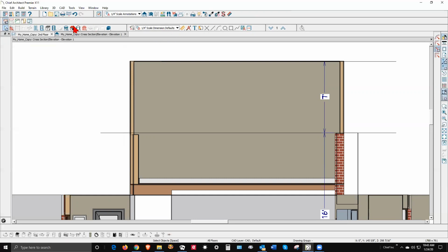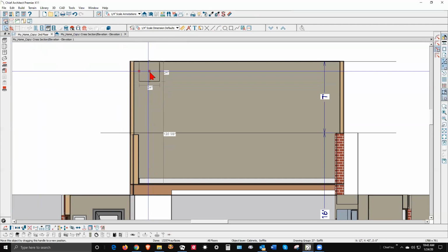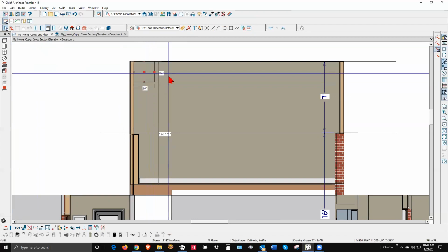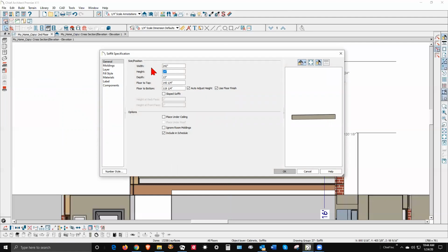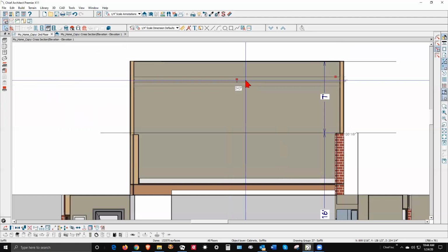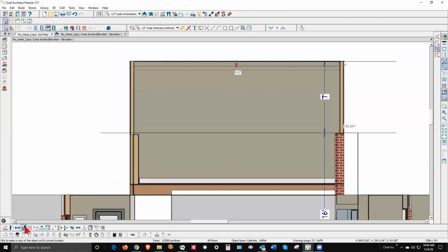So I'm going to try to construct a truss out of cabinets. The soffit tool is your friend here. I'm going to click a soffit in there, and we're going to shove this up against the ceiling. And I'm not going to try to exactly duplicate your truss. I'm just going to kind of give you the conceptual idea of how it would be done. I stretch this truss all the way across the room, and it's 24 high. I think we want about 6 inches high. And the depth is probably about 4 inches. And the width, I'm going to leave where it is. So now I've got, let's say, the upper chord of the truss. I'm going to pull that up to the ceiling and then copy it down to here.